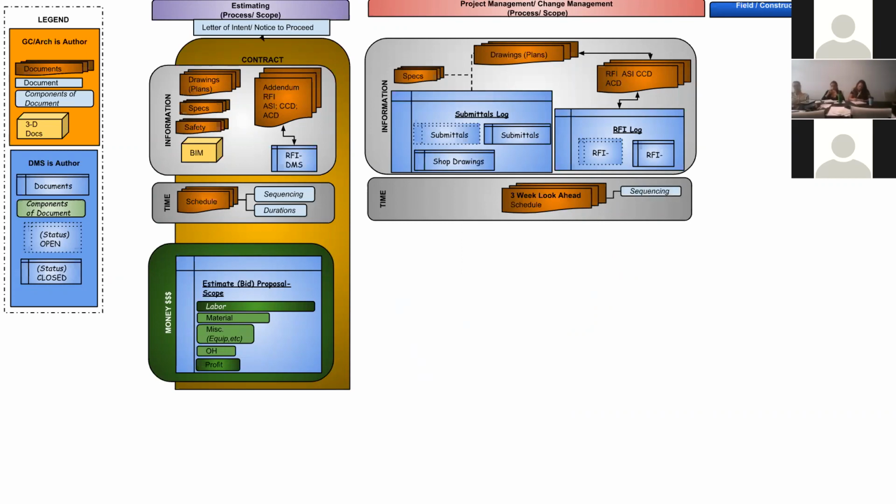Go what happened from the master schedule into the 3-week look ahead, and did our durations get affected? In regards to, let's just talk about durations for our scope of works. The general rule of thumb is on a master schedule, they will give us 10 days for framing per floor or area.